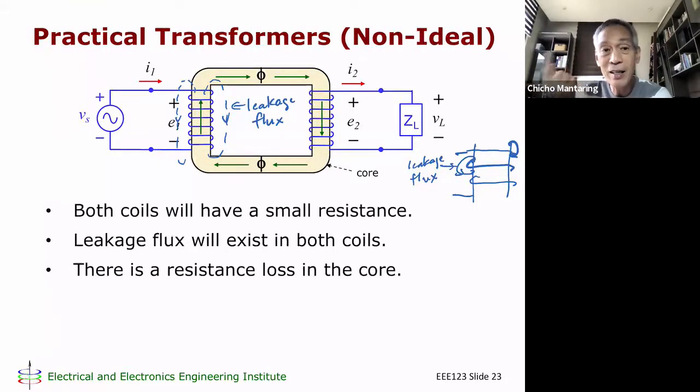These currents are circular currents. So if your flux is flowing, for example, here left to right, you have currents flowing around the core. You call those eddy currents. That's why eddy, because it goes around in circles.